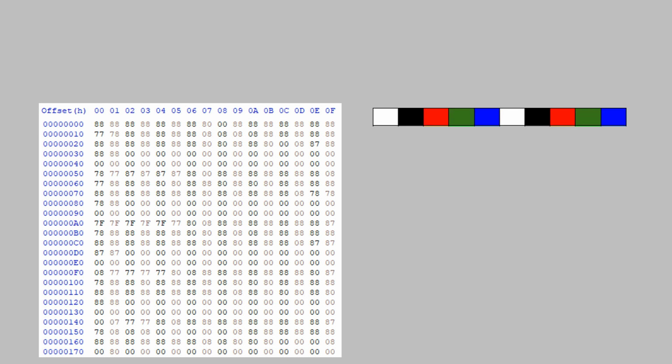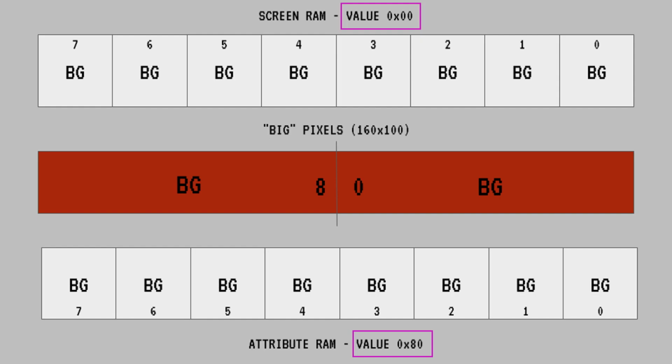So one attribute block always covers 2 pixels just as 1 byte does. The first pixel will always be the background color. If the second pixel is different, it is the foreground color. This is what we write to attribute RAM.